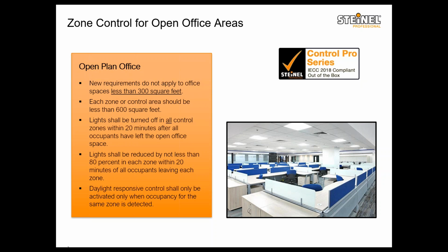The other two requirements that are mentioned for an open office area kind of go hand in hand. One says that all the lights should be turned off in all zones within 20 minutes after all occupants have left the open office space. And the other one says lights shall be reduced by not less than 80% in each zone within 20 minutes of all occupants leaving each zone.